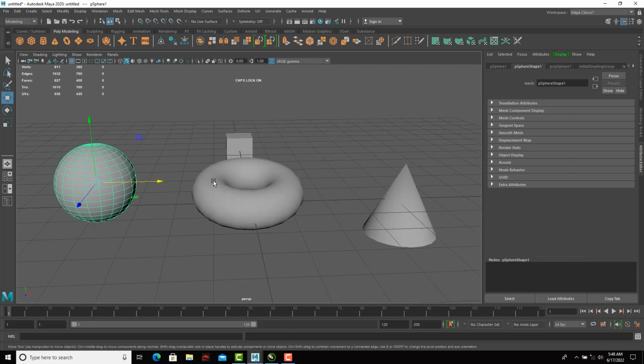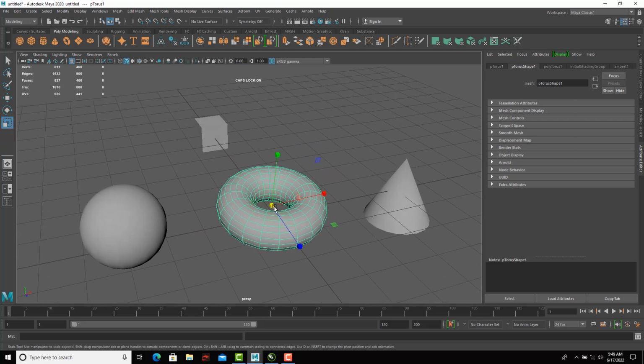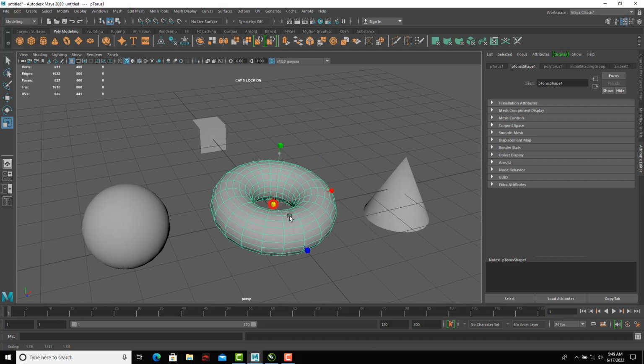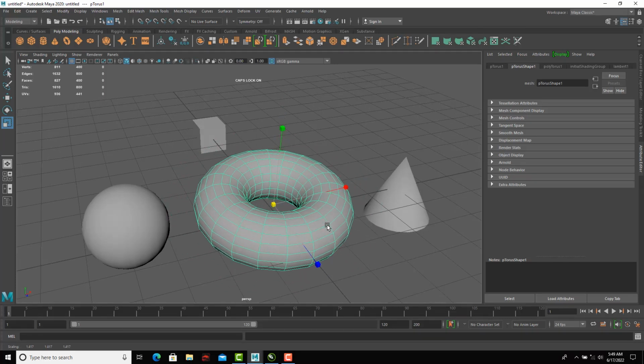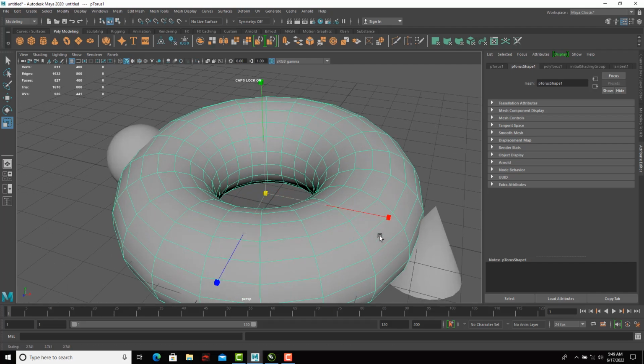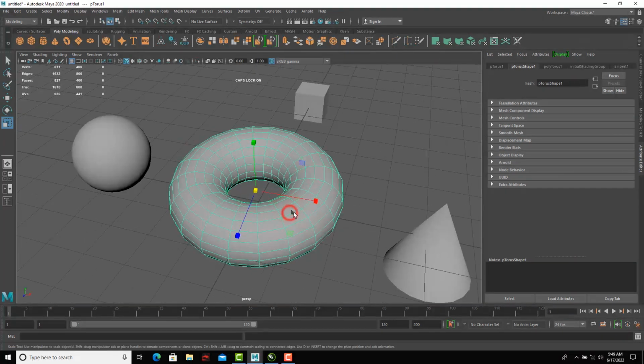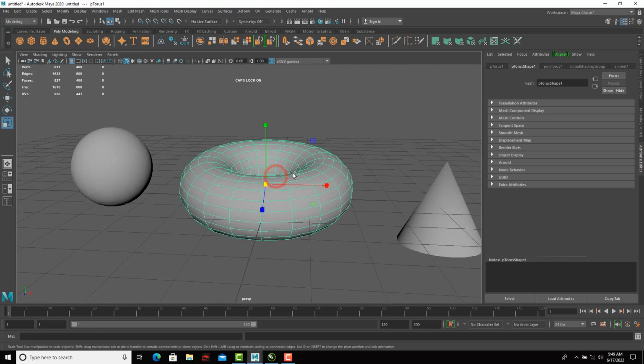Now if you want to work with scale tool, scale tool is all about making your objects bigger, right? Scaling it. So all you need to do is click on this particular icon, this guy, click on it. You can see we now have a different icon. So you click and scale, right? If you want to scale everything all together, you click on this middle mouse button and scale to make it big. You can also scale from one single side, which is either from your x-axis, y-axis, or z-axis.